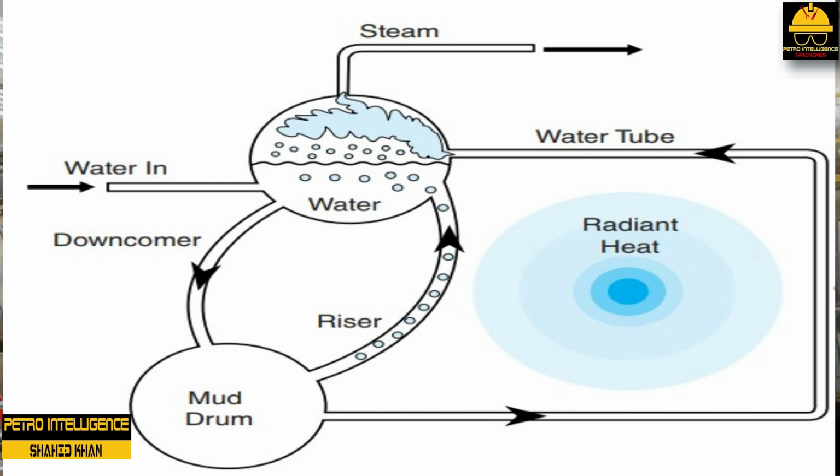Bubbles begin to form and rise in the water, increasing circulation and pressure as shown in the picture. This circulation rate can easily reach 2 million pounds per hour. At this point, approximately 65,000 pounds per hour of steam is being produced. Each time the water passes through the tubes, it picks up more heat energy. When the pressure increases to slightly above the system pressure, steam will flow through the non-return valve into the system. Boiler load is a term used to describe the plant's demand for steam.